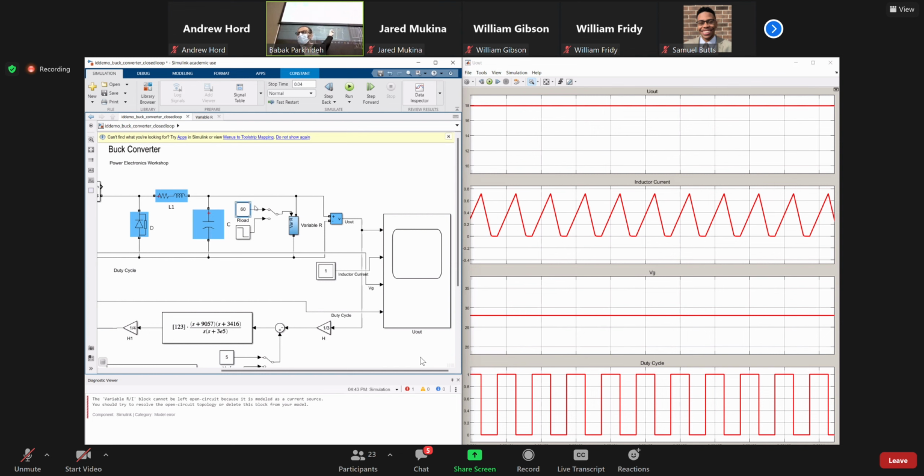The way that you design the L and C is for ripple. Okay? So if you go down designing those and their interaction, L and C are far from the resonant frequency, LC omega squared is far, far, far from the switching frequency omega.